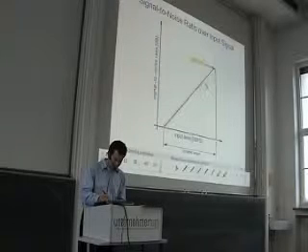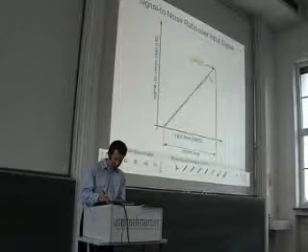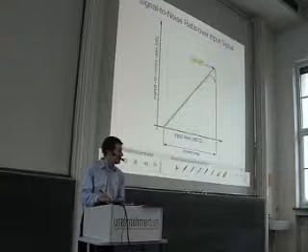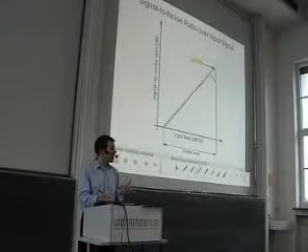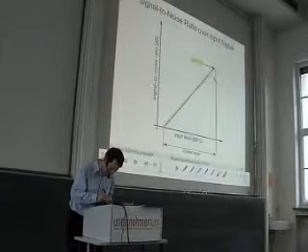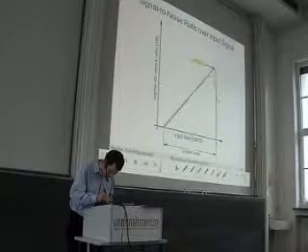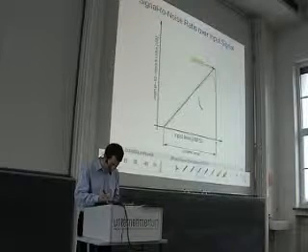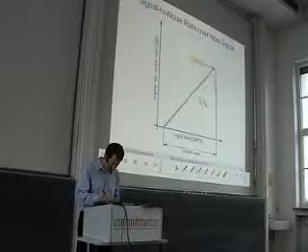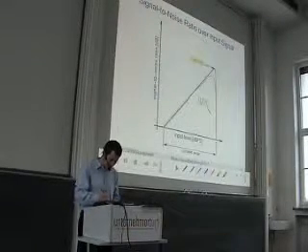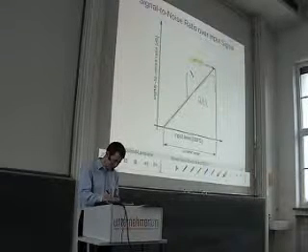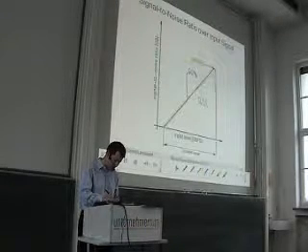The harmonics start to peak out of the noise floor. So there is a deviation of the SNR and the SNDR curve, and then you usually get something like this. So this is the signal to noise and distortion ratio, and the red one is the signal to noise ratio.